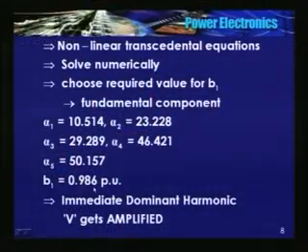See, I will repeat. If the V by F curve is known, depending upon the frequency of the fundamental, I can get the magnitude of the fundamental. That is nothing but B1. So you need to know the value of the fundamental that you want at a particular frequency. So I equated from a V by F curve B1 to be equal to 0.986 per unit.